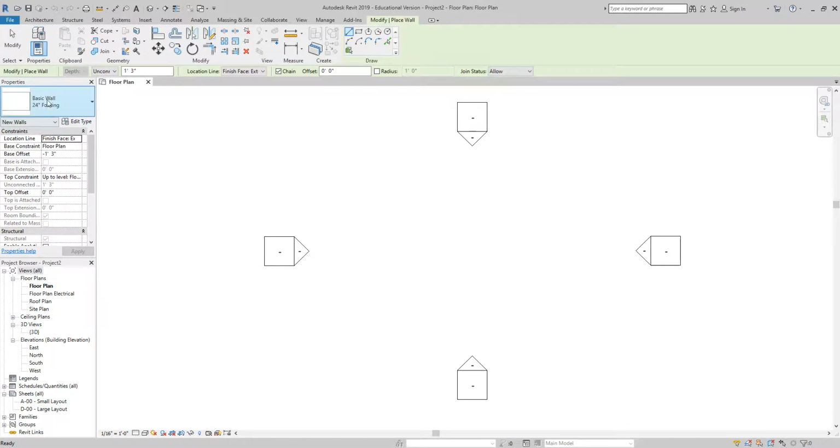The first thing we're going to do is, in our properties menu, set up what type of wall we need. We are not going to be drawing footings in this class, which is what occurs for the foundation of a house. We're going to start with our exterior walls. You can choose any of the 4 exterior walls. The only real difference is what surface is on the outside. I'm going to click the brick one because that'll make something easier to see later on.